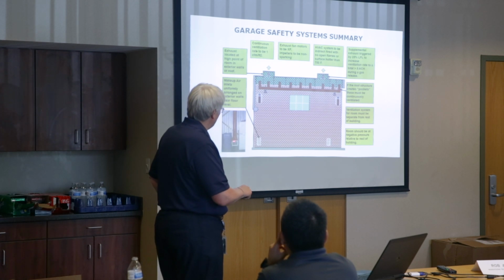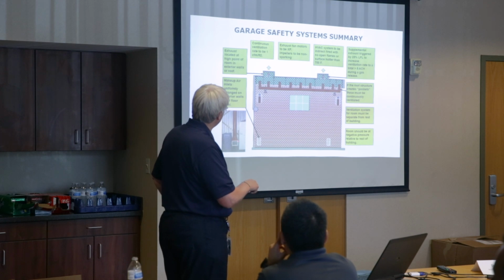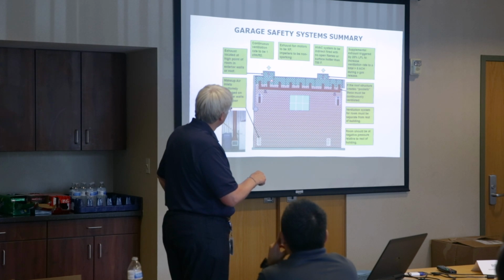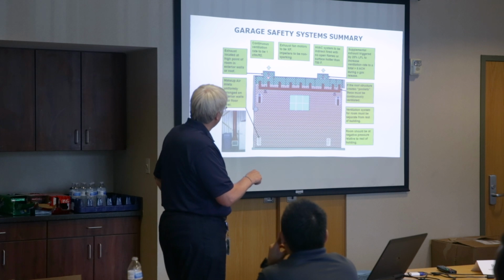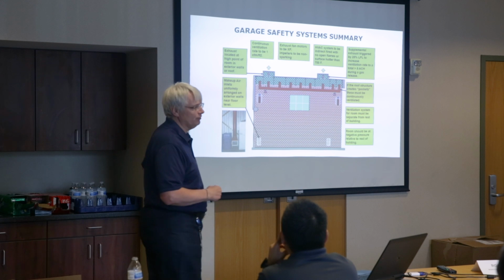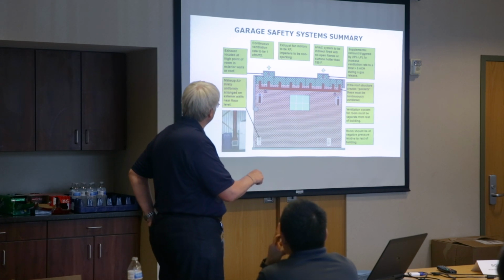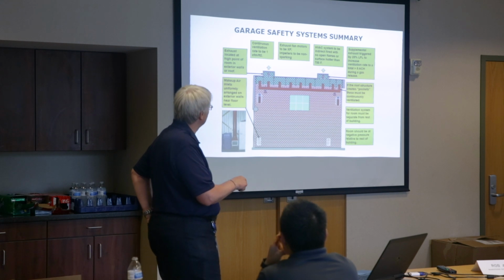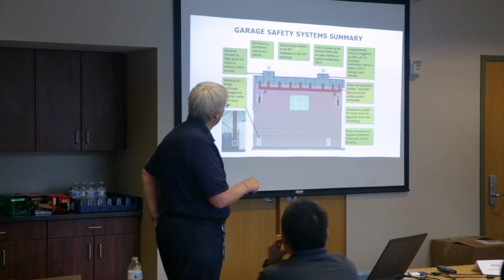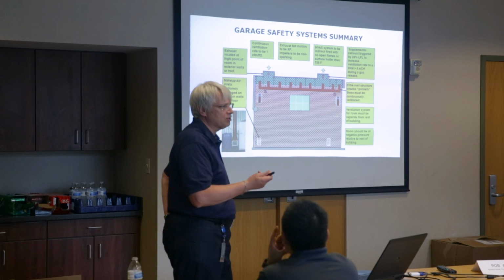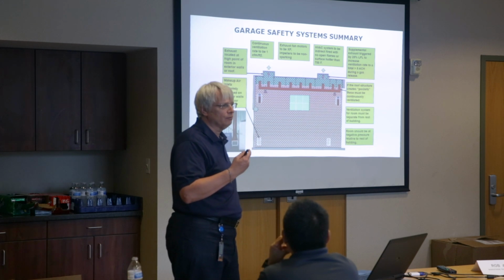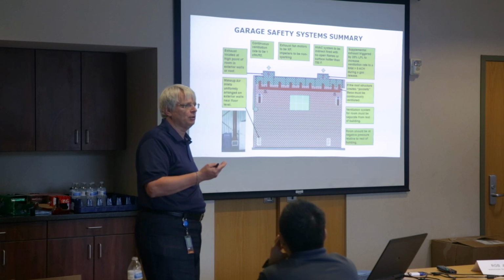So we've got our makeup air down near the floor, and it's heated. We're exhausting at the high point on exterior walls or roof. You can see here's an exhaust fan up here. This would be our continuous ventilation, at a rate of 1 CFM per square foot of floor area. So that's our continuous exhaust. We compare those two boxes.